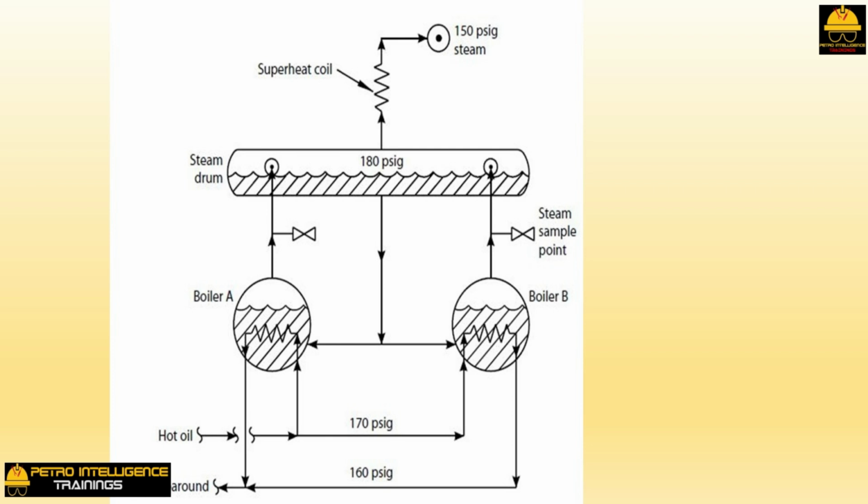The operators planned to bypass boilers A and B in turn, as shown in picture, to determine which boiler had a tube leak. Boiler A was arbitrarily selected. The hot gas oil pump around from the fractionator was closed. With the reduction in the gas oil pump around heat removal, the generation of 150 psi steam dropped in half, and the water intrusion into the fractionator stopped. The operators concluded that with waste heat boiler A out of service, and the water leak into the fractionator apparently eliminated, the leaking boiler was A.